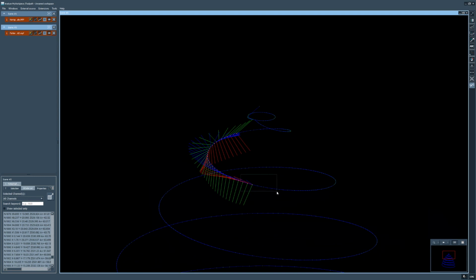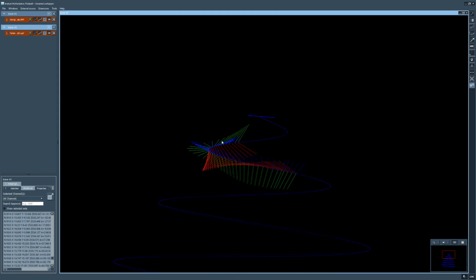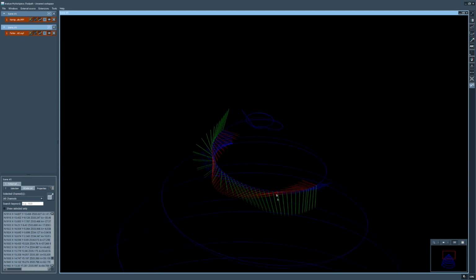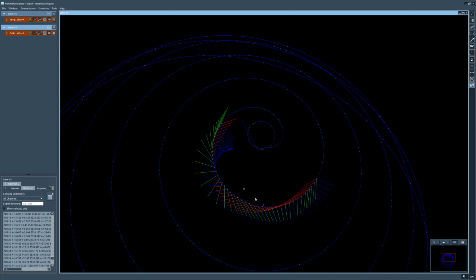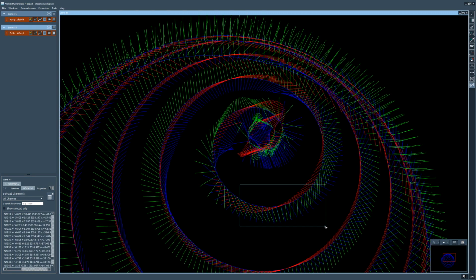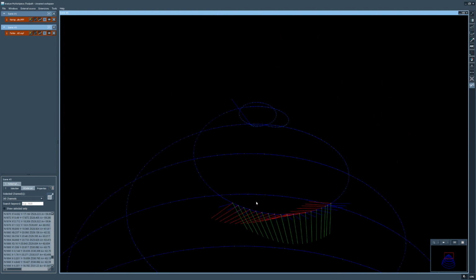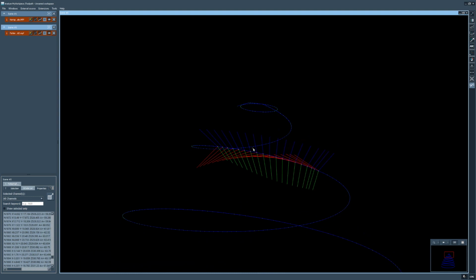And these are the ones you should look for, because areas like that could show you there is a quick change of orientation, especially in this area. Let's just select these few points here. And here we see there is a very quick change of orientation, and this in the end will probably also be visible on the workpiece you are producing.